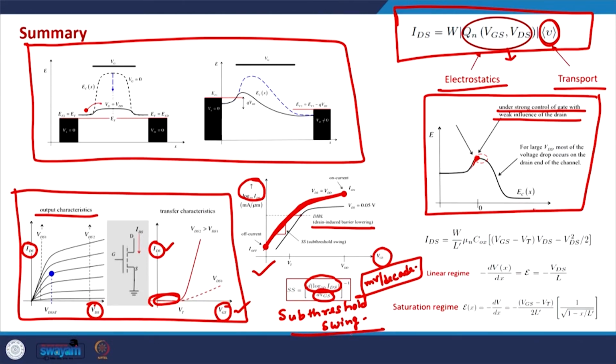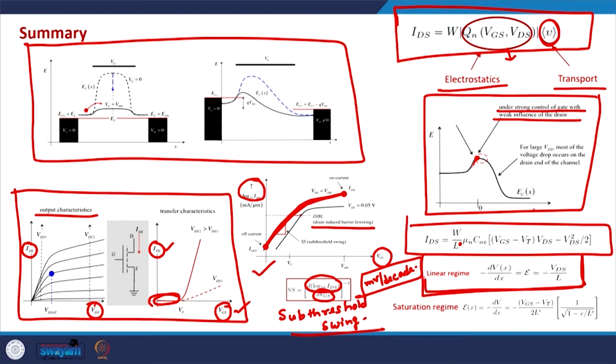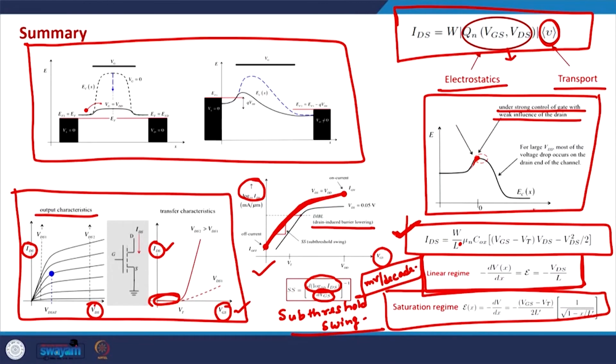After that we derived the traditional IV characteristics of the MOSFET, and this is how it looks like. We analyzed the characteristics of the MOSFET in the linear regime and in the saturation regime, and from this current expression itself we can derive the electric field and the voltage at any arbitrary point in the channel. But this treatment will not hold true in the case of ballistic MOSFETs or nano MOSFETs. So, that is why we need to properly understand the transport theory of the MOSFET.